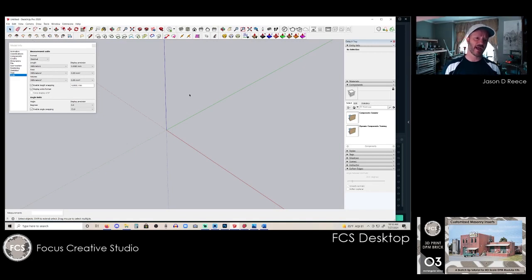After I get done with all that, we'll go through a session with 3D Builder. I'm going to do this in pieces where I export one or two of those models through 3D Builder so that you can see it actually flip faces when it's correcting a problem. You don't always catch all of them in the modeling. It doesn't show up in SketchUp. So that corrects your STL file.